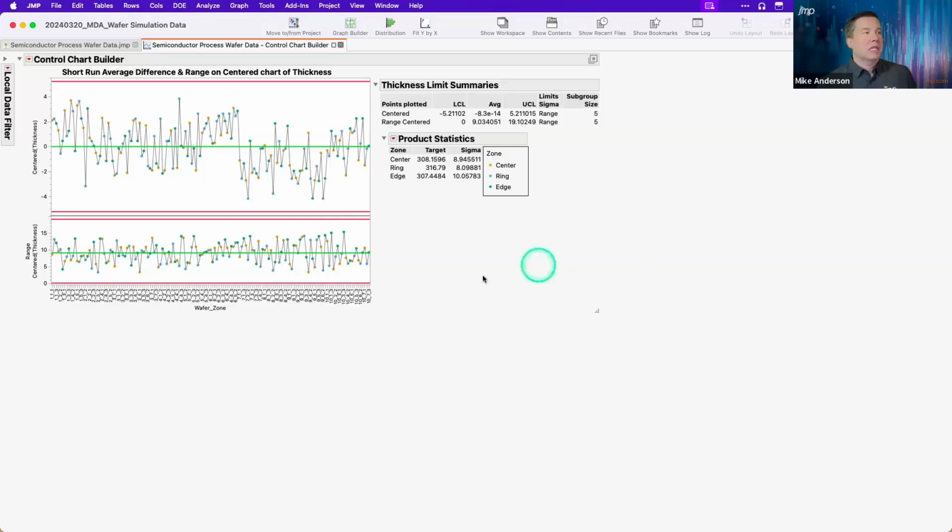They're all the same flavor of chart. And the thing that makes them interesting is we're not going to look directly at the average value, for instance. We're going to look at the deviation of each sample subgroup from that average. In this case, I've made some pseudo products within the wafer. For those of us in the industry, this idea of segmenting a wafer into different sized rings or quadrants or different shapes when we want to monitor different things is not that groundbreaking. What's unique here is we're putting it all on one control chart and treating it as one data stream, because it is.